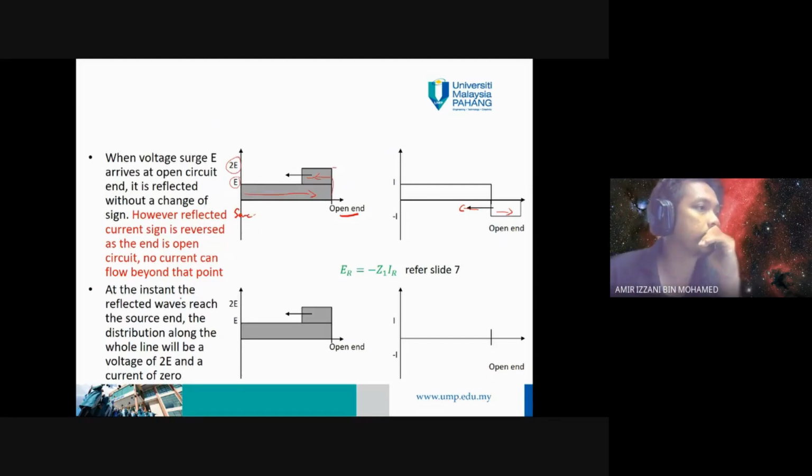At the instant the reflected wave reaches the source end, the distribution along the whole line will be 2E and current 0. So no current here. This is the V curve, this is the I curve.